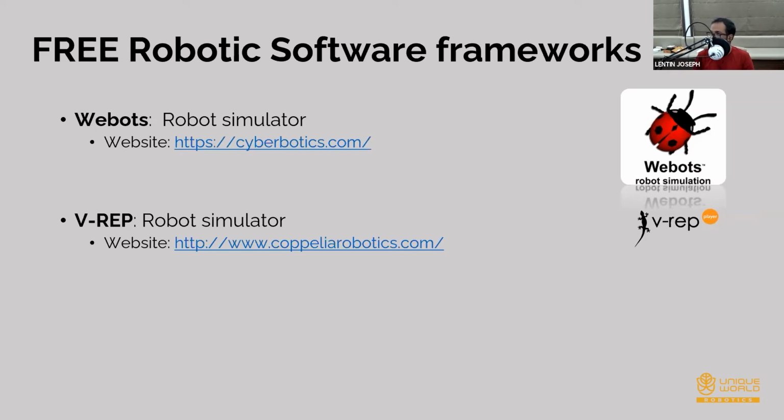Okay, the next question is, what is the difference between PCL and PCL2, which we see in RViz? It is actually a different ROS message. I mean, not a basic question. PCL was an old ROS message used in previous ROS distributions, but currently we are using PointCloud2, which is mainly for visualization purposes. So PointCloud2 is what we are using in the latest distribution. PCL is just an old one. That's it.